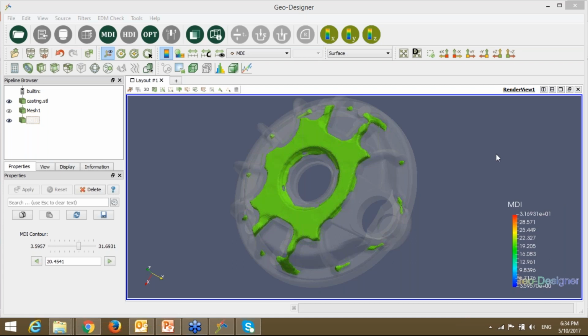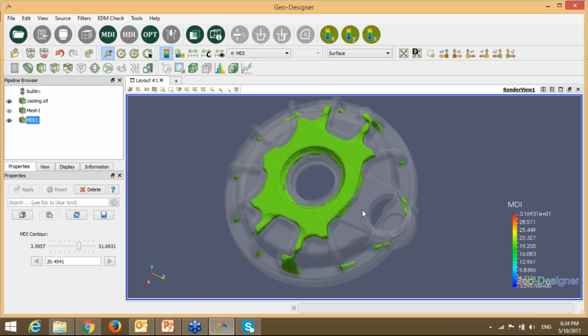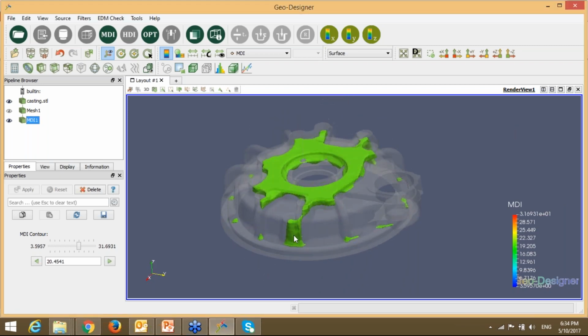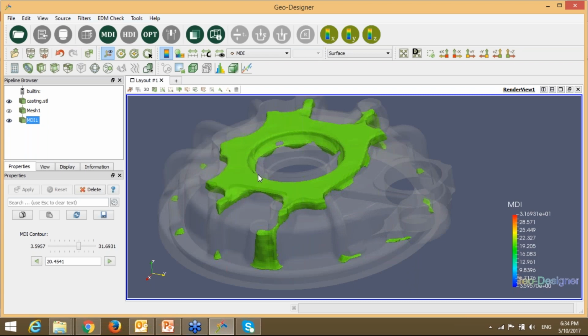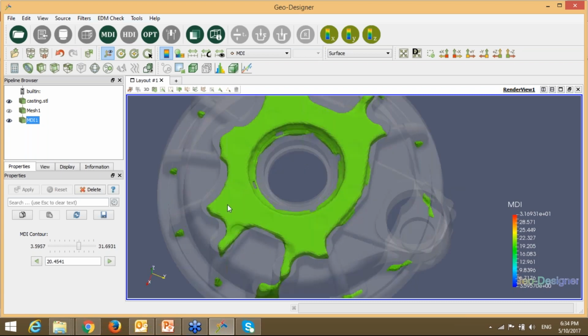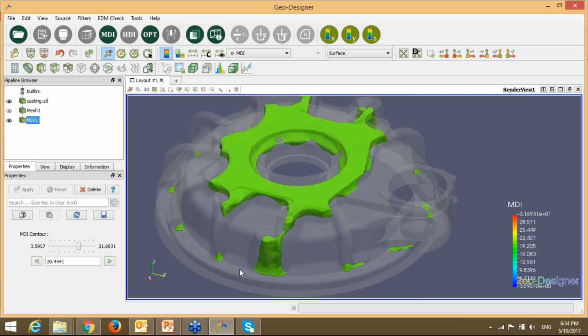Accordingly you should decide the location of your riser and chill. Another thing is how we decide the point required for a chill or a riser, or whether just hot metal through an ingot is enough. No, this is specified from the size of the mass. What you see here is that if you see the mass available in the color here and compare it with this location, it is very high. That means this location on the top side will certainly require a riser or a sleeve.